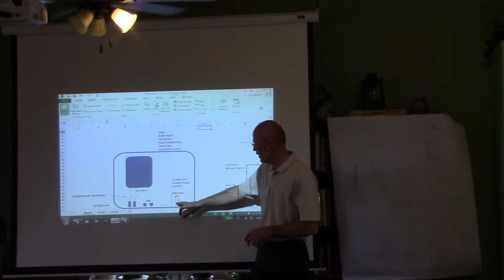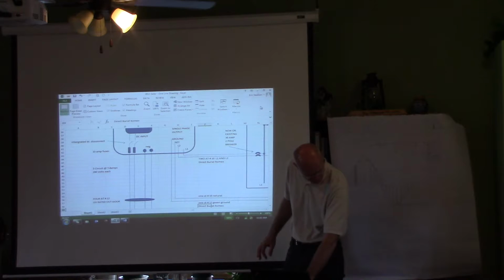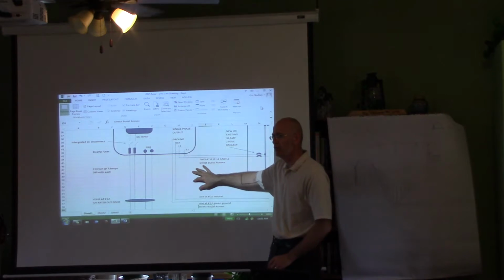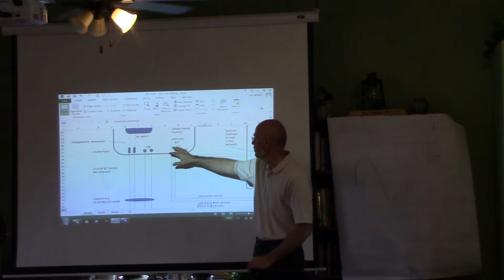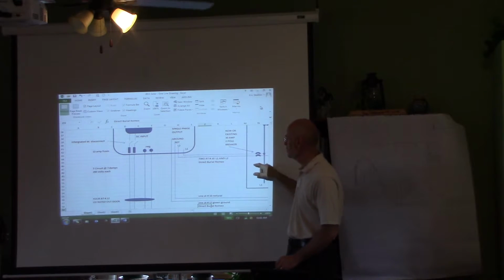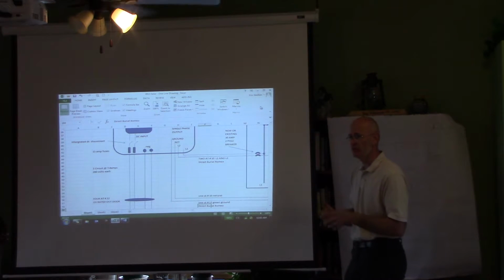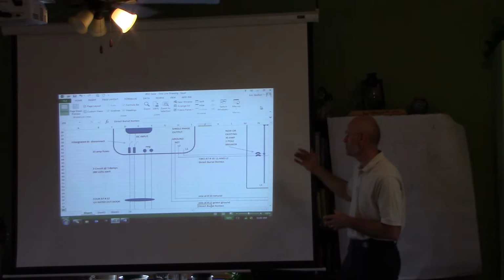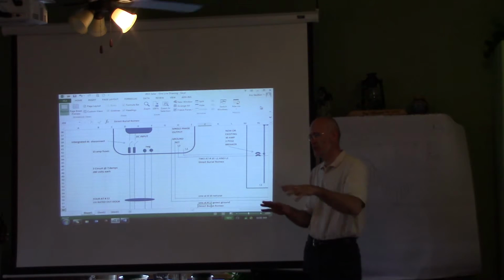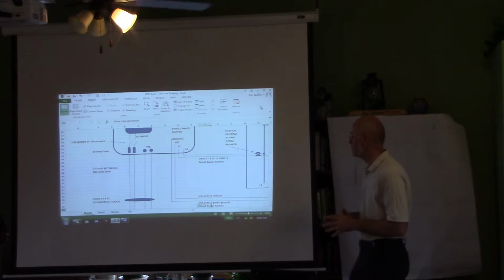And then we've got a wire from the inverter. This is the next topic on your list here, connection to the house. You're gonna probably bury a wire, Mark, right? Is that what I've heard you guys say? You're gonna bury a wire from the inverter into the house and connect it to a new breaker in the house. So that's why we said direct burial Romex here, for the electrical inspector, to explain to them what we plan on doing. I didn't draw a site plan for Eric. That's your guys' thing and where you're gonna position it. He knew how to do that, he knew where he wanted it. You guys know what trees to take down if they're in the way.